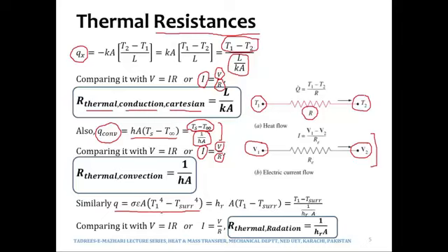We had performed the factorization of a⁴ minus b⁴. It was (a² plus b²) and then (a² minus b²). And then we had performed factorization for a² minus b². It was (a plus b) times (a minus b). And then we had separated the area along with ΔT. So whatever was left was the radiative heat transfer coefficient h_r.